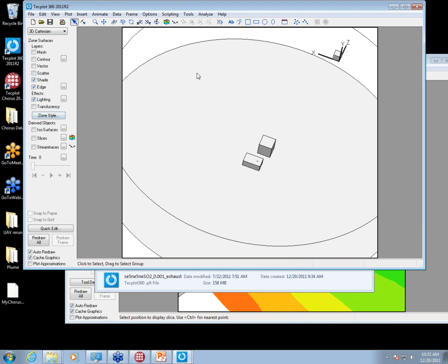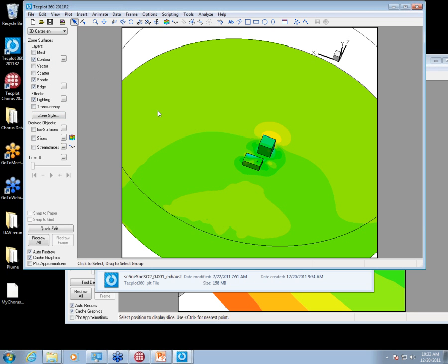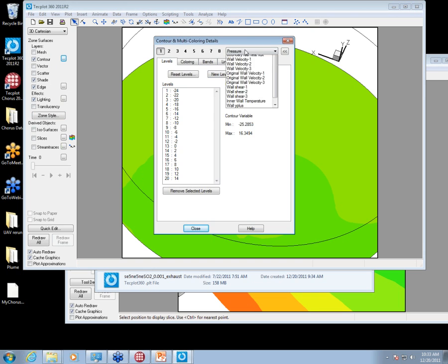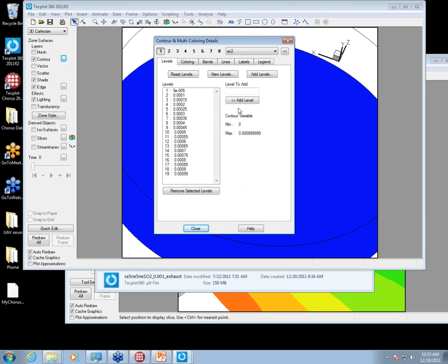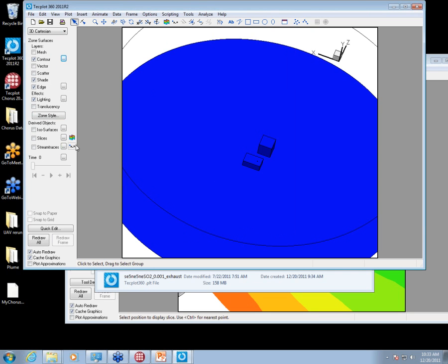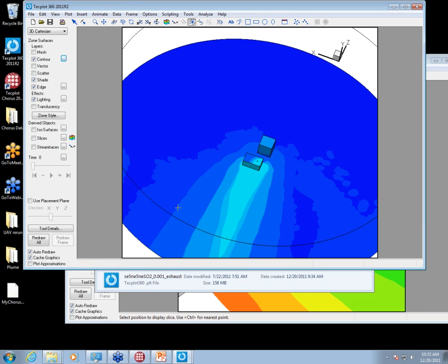And so I'm going to pop into, you can see the contour pressure. It's really not that relevant for this particular example. What we do care about is the SO2 concentration. You can see it's very low. And I don't know which one I chose, but we can again go through and you can just start to add some contour levels just by clicking on the flow domain. And what we're doing is really just refining the fine structure. And since we're talking about extraordinarily low concentrations of SO2 gas, you need to do that.